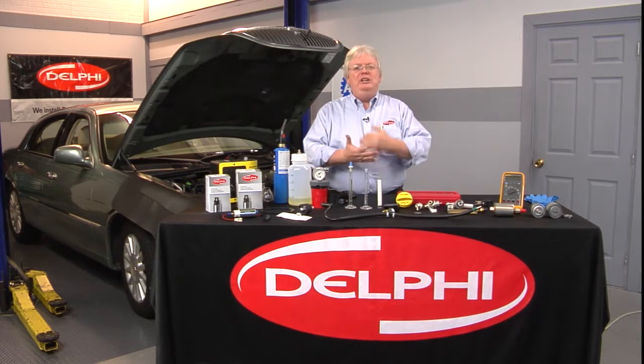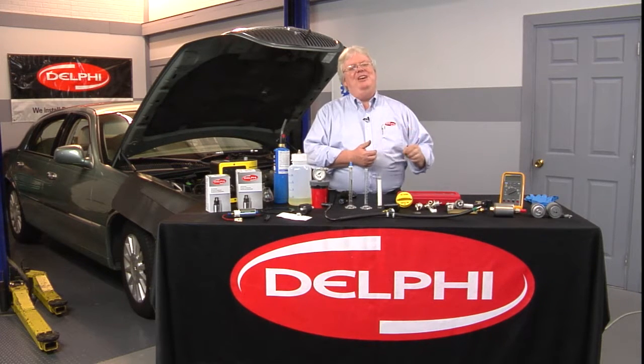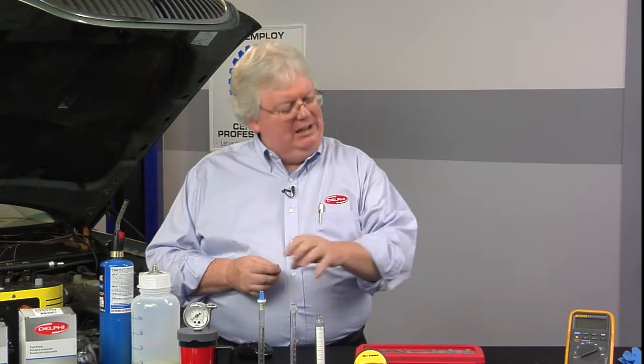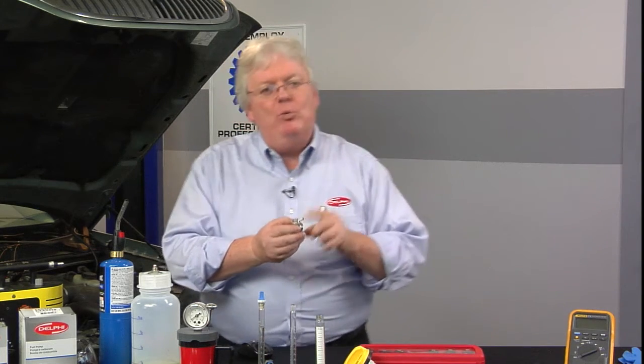Diluted engine oil. Anytime you have a PCV system pulling crankcase vapors, if those crankcase vapors of oil also have a bunch of gasoline from a drippy injector or some other issue, got gas in the crankcase, you'll have the rich codes. Vacuum controlled pressure regulator. We talked about the pressure regulator, maybe the wrong pressure, but it also can just be a rupture.